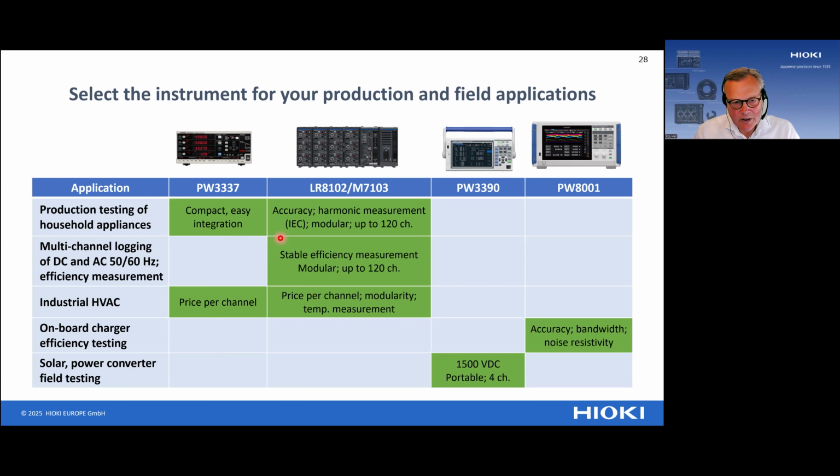Okay, and then another application which is worth mentioning is the PW8001 for onboard chargers and efficiency testing. And this one is particularly interesting for that application because in that situation you have the high switching semiconductors integrated in the circuitry, and they create noise, and therefore you need to have a very good noise resistivity, but you also need the high accuracy to be able to measure the efficiency of this kind of devices.